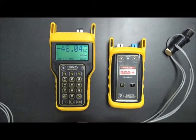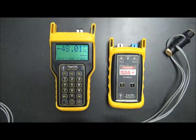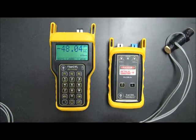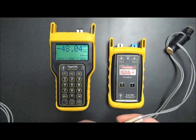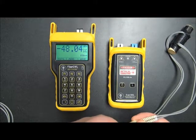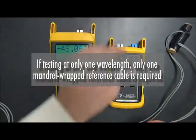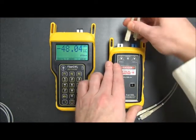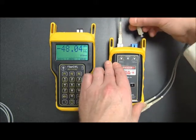And as you can see, I've taken a duplex cable and wrapped it around a mandrel so that it's a lot easier to handle one mandrel with two cables on it than it is to handle two separate reference cables and two separate mandrels. The reason we need two reference cables is because we have two wavelength ports here. So I will connect these into the light source first.